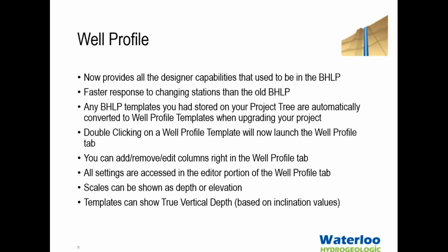So now let's move on to the next module, the well profile. So the well profile has been updated so that it contains all of the designer capabilities that used to be in the separate BHLP or borehole log plotter module. So again, you're going to find that the well profile is having a much faster response time when you are changing stations as you're flipping through the stations than when you were using the old BHLP module.